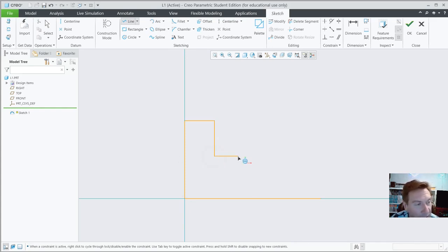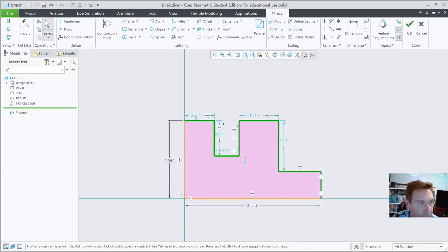Click, drag this across here. Stay away from equals. Click, drag this up. This can actually be equal to that other line. So this is where it will work out okay. Now this next one, do not make it equal. Click, drag it down a bit further. No equals. Click, drag across, and infer to that end of that line. Click, and now connect it. And now middle click 1 time. Middle click a 2nd time, and the dimensions will appear.